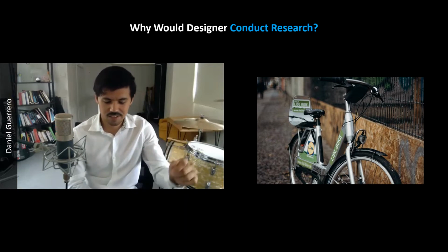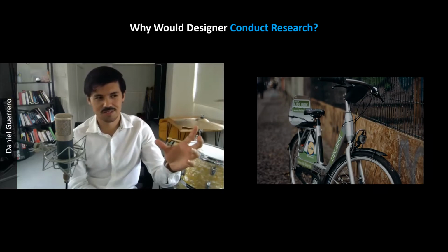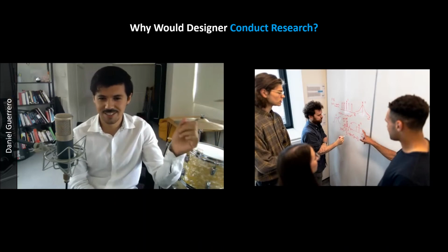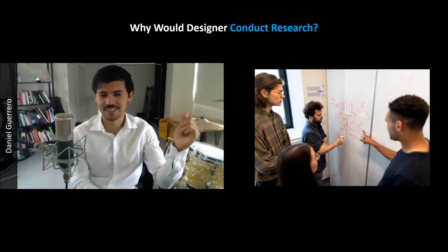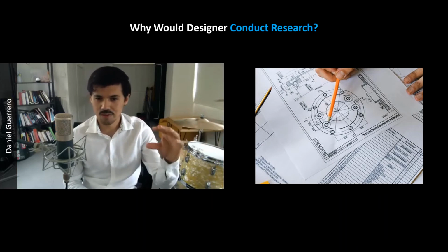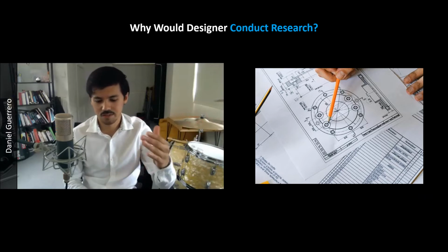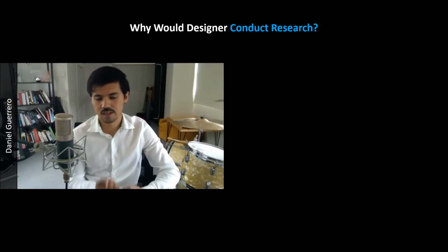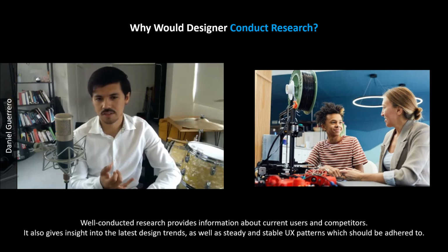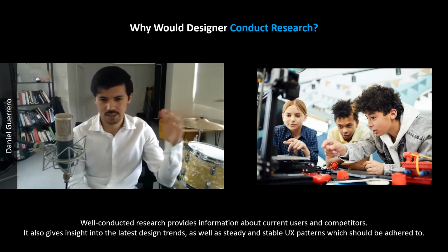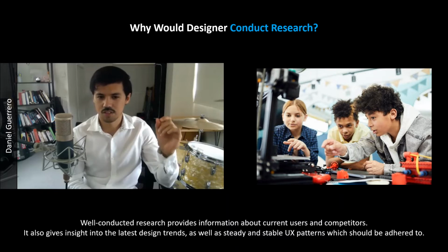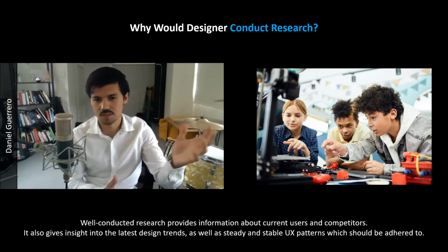But the interesting part is that you don't design just a spring. You need to follow a formula. So you need to do the research of what this formula involves, and then you go to the materials, and you find the data sheet of the material, like the heat resistance, the flexibility, the deformation. You need to consider all these variables and then put them in the formula and start getting results, changing your design again if something is not working properly.